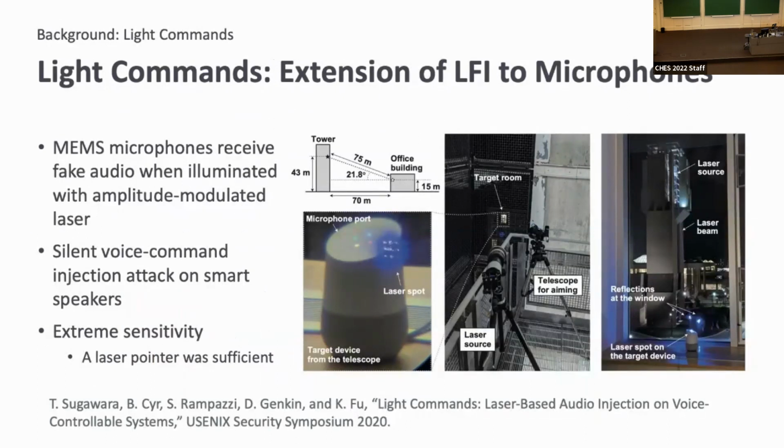Some years ago, we proposed Light Commands, which is an extension of laser photoinjection, to microphones. MEMS microphones receive fake audio when illuminated with an amplitude-modulated laser, which results in silent voice command injection attack on smart speakers. An ASIC inside a microphone package was one of the causes. We were surprised with its extreme sensitivity. A weak continuous wave laser, similar to a laser pointer, was sufficient for the attack.